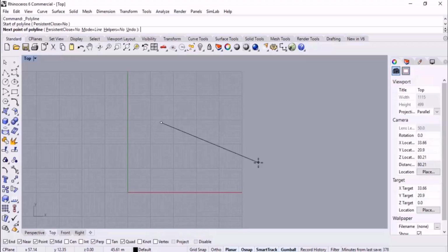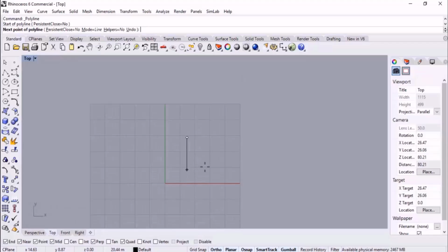But for those who do not know AutoCAD, if you activate ortho, it restricts the movement of the cursor to multiples of a specified angle from the last point created. Actually, in 4 directions, left and right, up and down. And you can start the command by using F8. You can either click on the icon of ortho, or you can press down F8 to specify the angle at which the movement of the cursor is restricted when ortho mode is active.